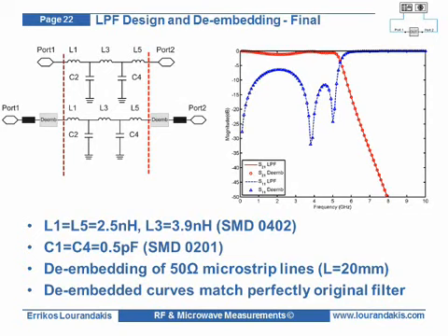Applying now the discussed de-embedding procedure to our low-pass filter example and comparing the DUT low-pass with the performance of the PCB low-pass, we get the S parameter sets shown here. It is interesting to note that the two sets of curves match perfectly. We have demonstrated now that when performed carefully, the de-embedding procedure is a powerful tool when characterizing prototype microwave networks.